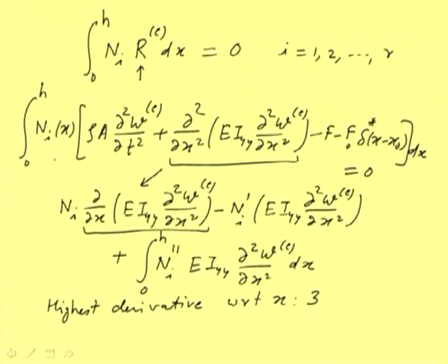So once we obtain the displacement, now we should substitute those into the equation of motion, and that will give us the elemental equation. So we will be using these equations which we already obtained earlier. Here you can see that the I subscript is there, which is varying now from 1 to 3 to 4, because now we have 4 shape functions, so it will be varying up to 4.